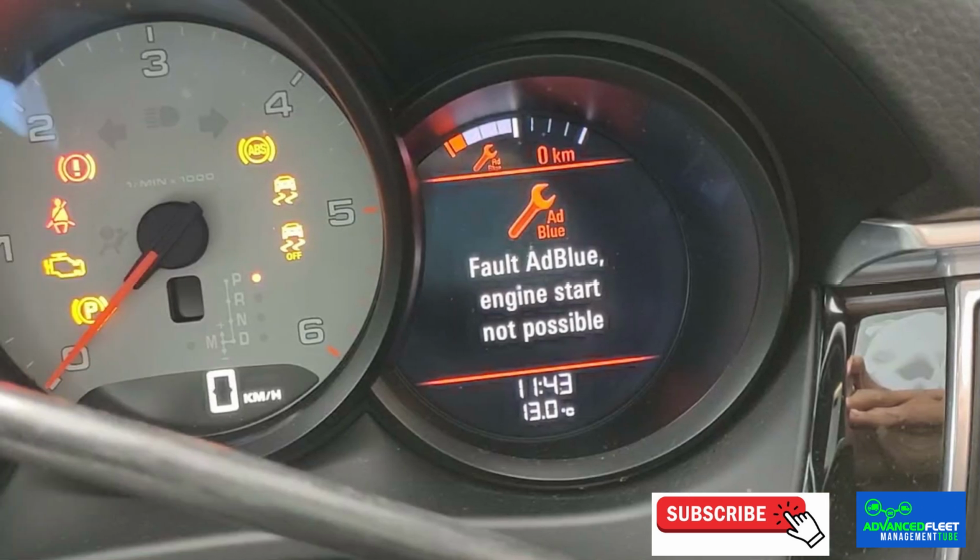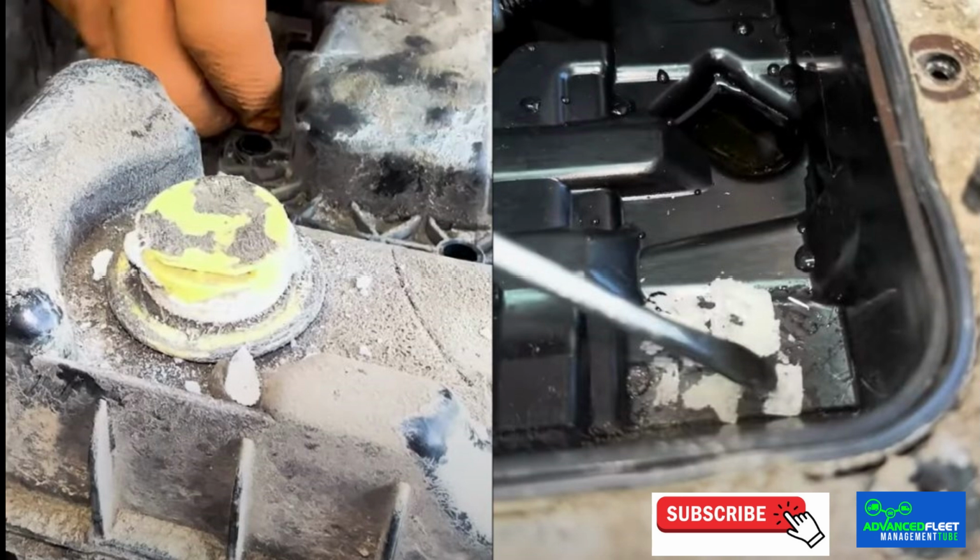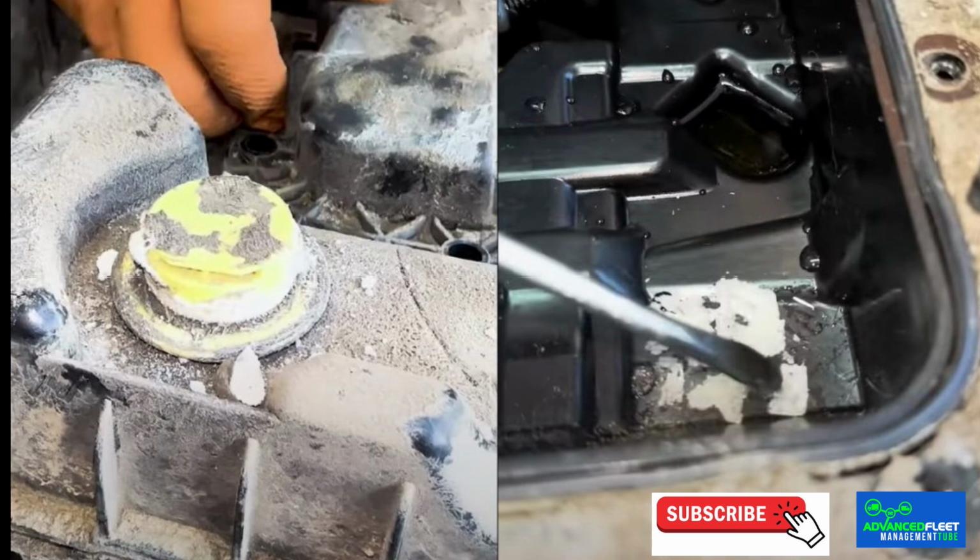Adblue sensors can stop working properly if crystals build up or there is contamination in the system. This can trigger alerts on the vehicle's control panel and activate warning lights indicating a problem in the system. Adblue crystallization. Crystallization is a common problem, especially in cold climates, where low temperatures can cause crystals to form and clog the car's injectors and system piping, affecting the effectiveness of the emission reduction system.